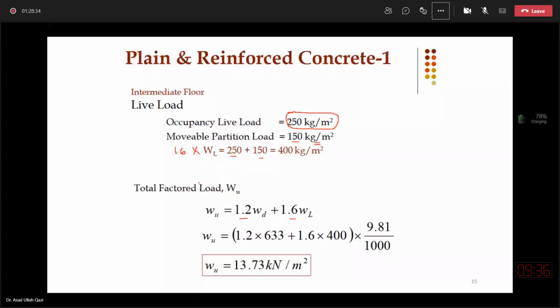It is normally decided based on the type of the building how much alterations or variations they are going to make, and whether the partitions will remain the same lightweight ones, or they may altogether change the type of partition. So in this way, normally exact drawings are required, and the location of the walls, type, thickness, and height are known, and then using the densities, we can calculate the load of total additional walls,